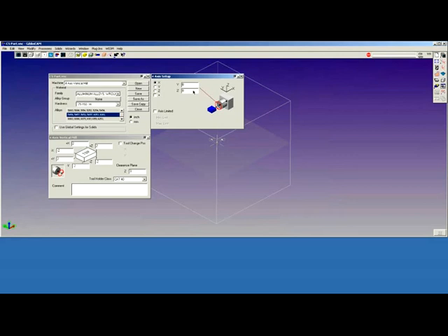When setting up your tools, the tool length offsets are set to the center of rotation, and all the Z values are positive, based on the touch-off point being the center of rotation. All right, so that's what we're going to be dealing with here.